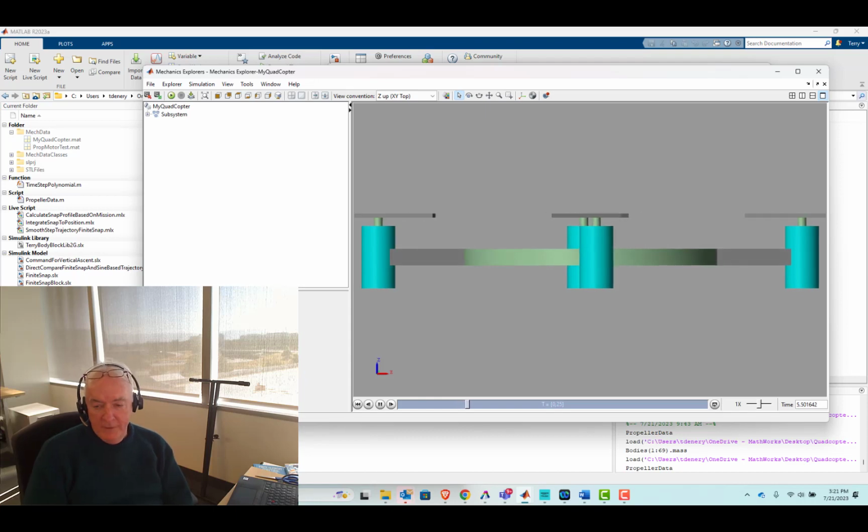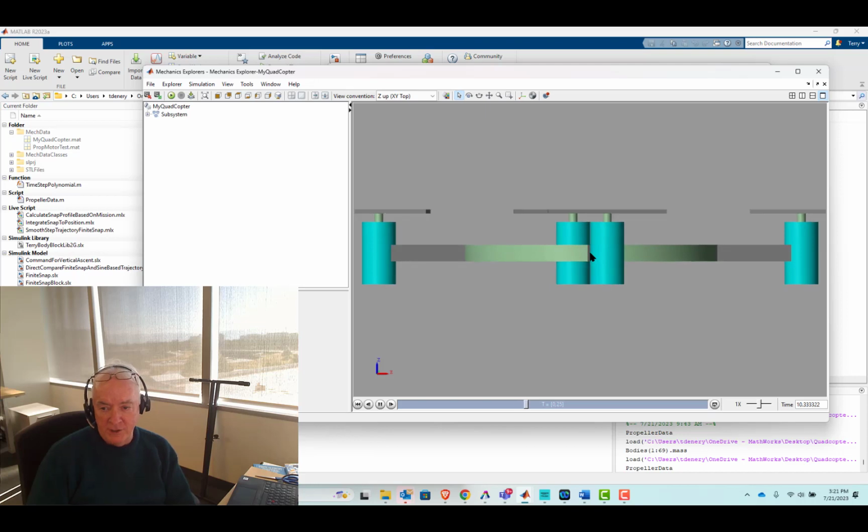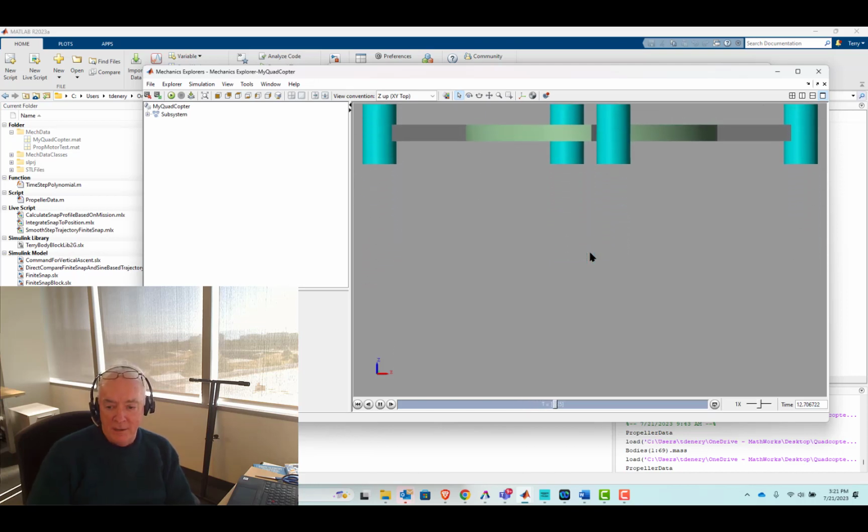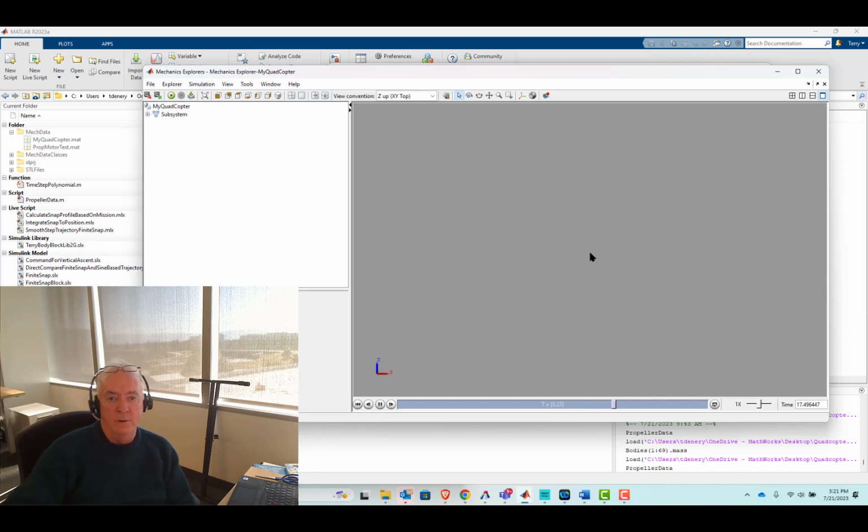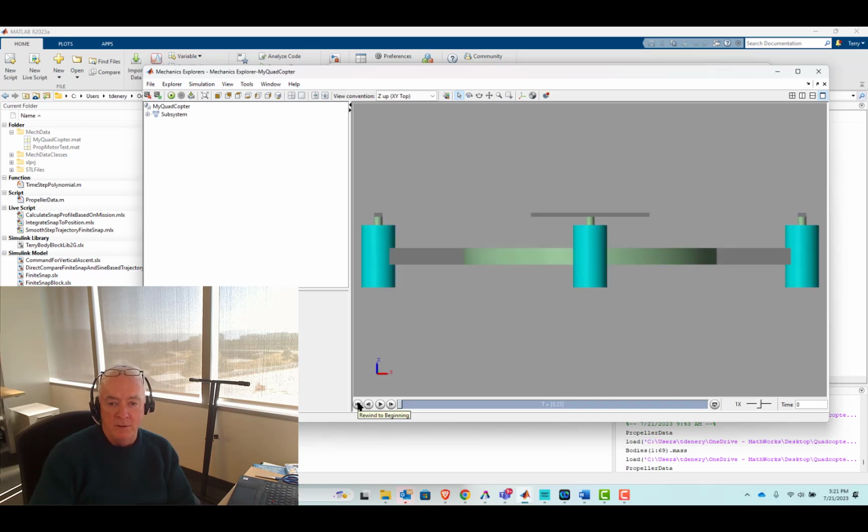So anyways, in this video, I'm going to fix this. You can see that slow rotation. I was able to track down that bug. But mostly what we're going to do is put in the vehicle measurements: what's its altitude, what's its essentially three-dimensional position, which for right now we'll express in XYZ according to a reference coordinate frame, the world reference coordinate frame, right? And we'll do a little bit more on the measurement, including orientation as well as velocity and angular velocity. Okay.